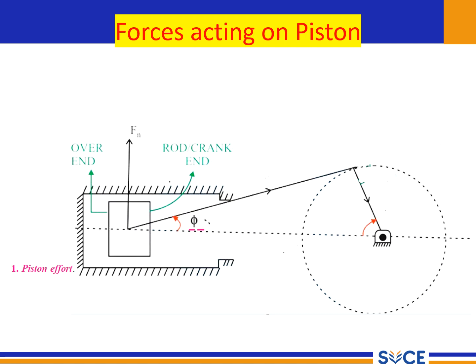Previously, we looked at an introduction to inertia, and what dynamic force analysis is. In the second video, we are looking at the dynamic force analysis acting on the IC engine. So initially, as we discussed in the last video, we are going to calculate the net piston load, which is FP. It is nothing but FL minus FI.